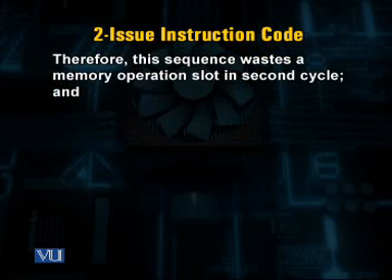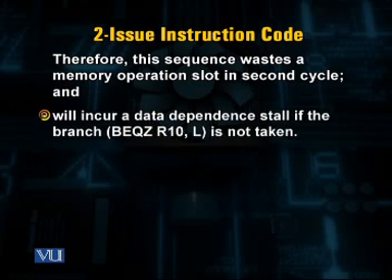Therefore, this sequence wastes a memory operation slot in the second cycle. Moreover, it will incur a data dependent stall if the branch condition is not taken.